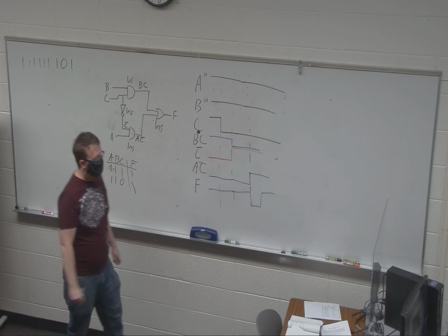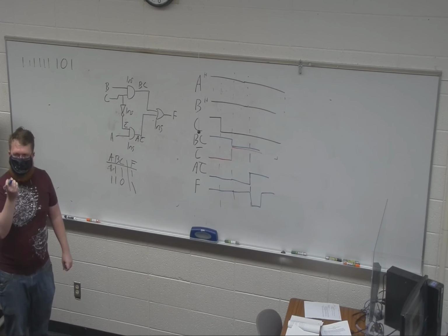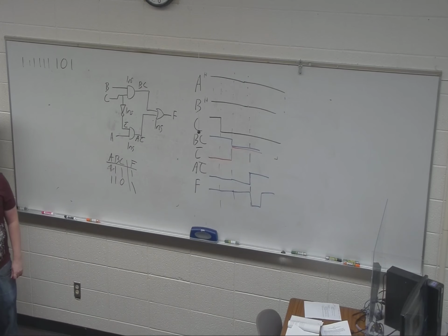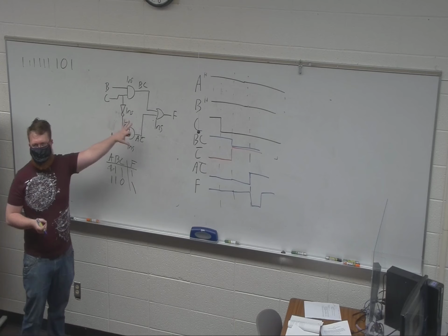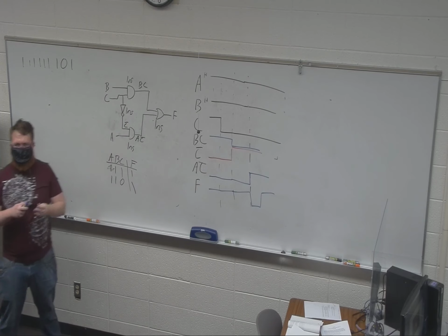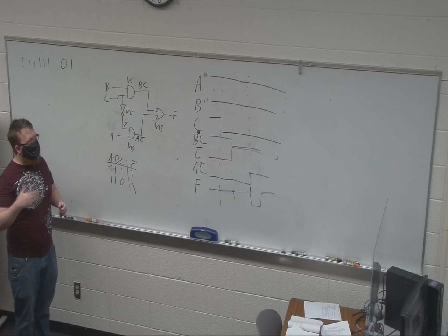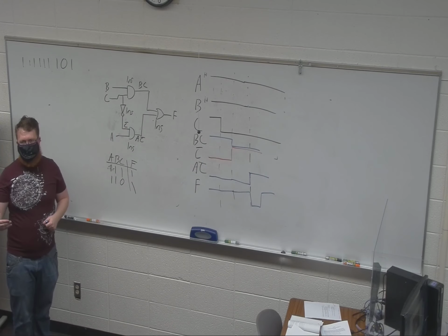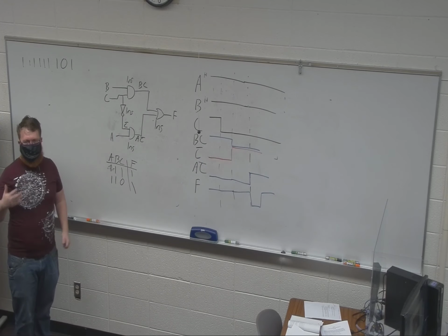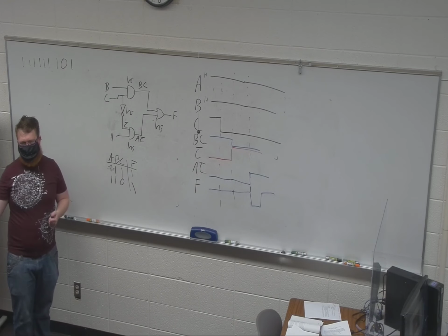So you get this one nanosecond where it's the wrong value, right? And that's doing some weird stuff, assuming the same delays are all there. And 1 nanosecond is really long. But this type of thing will really happen in systems, where you're going to have these kinds of dynamic changes where you want it to stay 1 and it just doesn't.